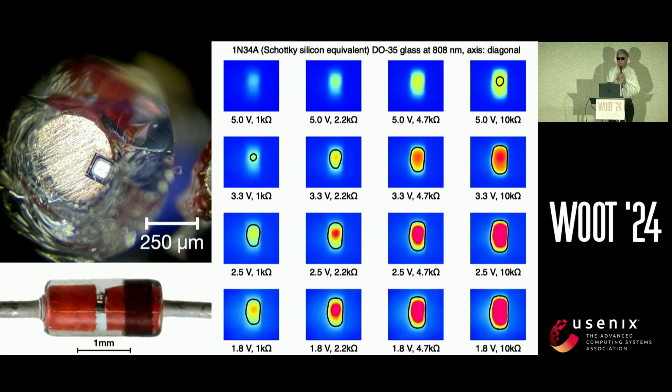But I don't want to give you the impression that it's only LEDs. It's not only status indicators. The definition of accessible PN junction is wider than that. For example, we found that electrostatic discharge protection devices, ESD, components on communication buses, which are there because communication buses are susceptible to ESD damage, are lots more sensitive than LEDs.